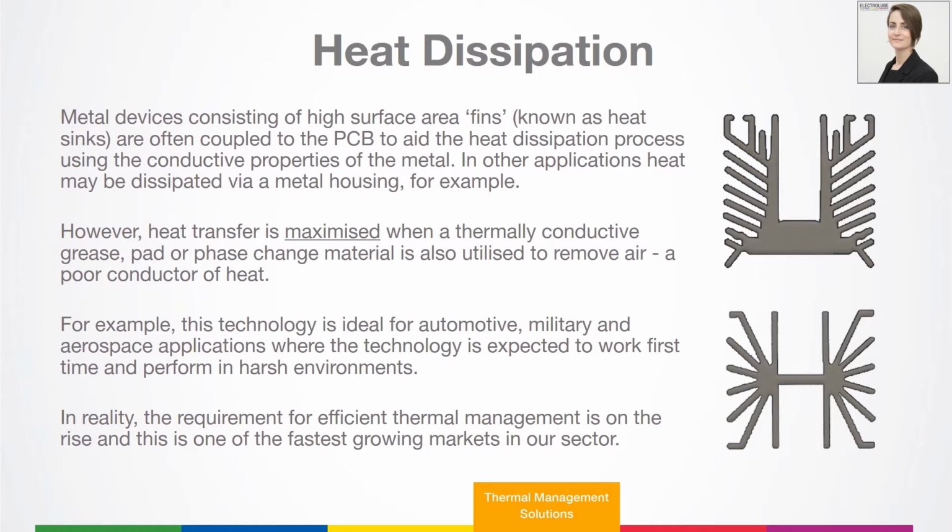And within these surface imperfections, you will introduce air at the interface, and air is a very poor conductor of heat. As a result, if you put a thermal interface material between them, something that is thermally conductive, like a grease or phase change material, for example, that eliminates all of the air from the interface and replaces it with something that is thermally conductive, that transfers the heat. This maximises heat dissipation and ensures that you're running at the lowest possible temperature for that device.